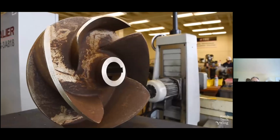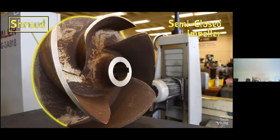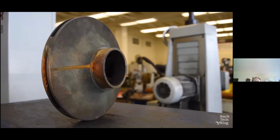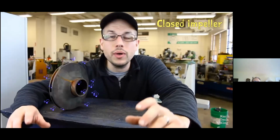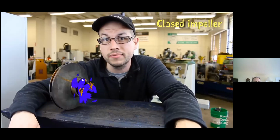If the vanes are mounted on a backing plate called a shroud, then the impeller is a semi-closed impeller. Then it's a closed impeller, because the fluid is directed through very well-defined pathways. That means that more of the fluid is pumped out into the system and less of it is just recirculated around and around inside of the pump. Of course, the trade-off is that they can very easily get clogged with debris.